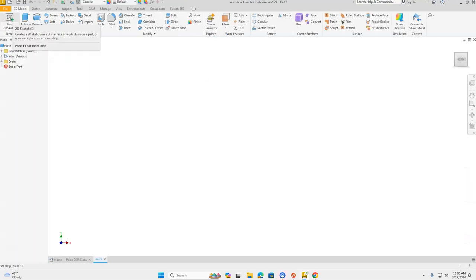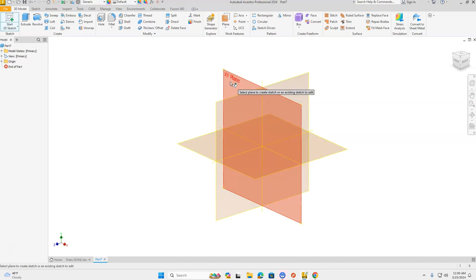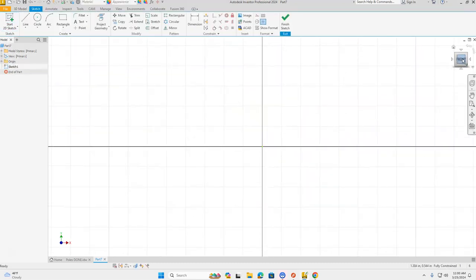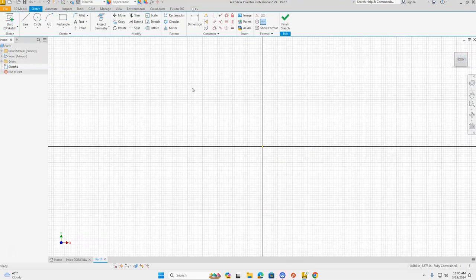2D Sketch, the drawing with the green plus mark, and we're going to select that for our XY plane. Front in your World View Cube, click your rectangle tool, start at your origin when you get your green dot, stretch out your rectangle. Now remember, this one had a radius of 1, so for our horizontal dimension at the top, we're going to type 1, press the Tab key, and then the length of this rectangle is 36 inches. Press Enter on the keyboard.